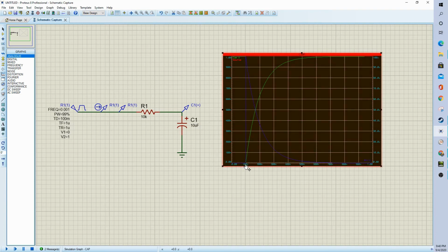And then as the voltage in the capacitor rises, the current feeding it drops. And so the higher the voltage at the capacitor, the less potential there is, which means less current's being drawn until it actually works its way down in this asymptotic curve to near zero. Now, one could argue that there's always a little bit of current due to leakage and the diminishing return problem, but as they say in engineering, it's not just good, it's good enough.